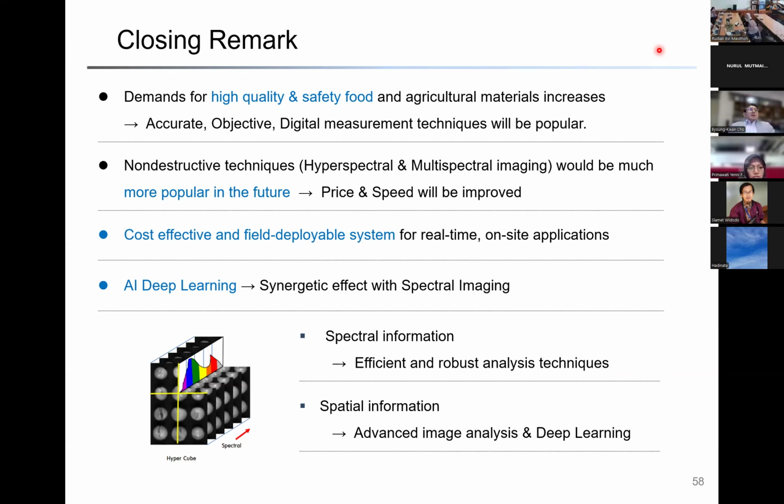You don't have to measure the white reference many times. I mean, the shape of your white reference spectrum is okay, but if the environment is changing, like the temperature changing, we need to measure again, because the intensity may be different, right? So I recommend frequent calibration.